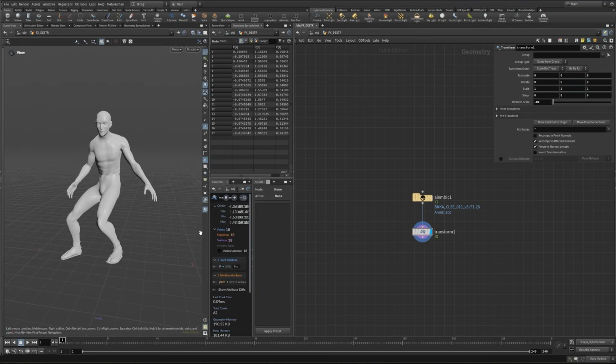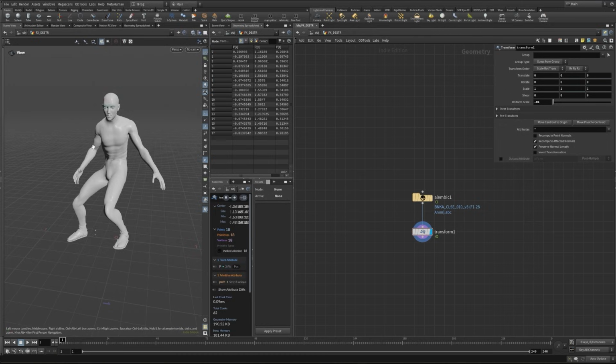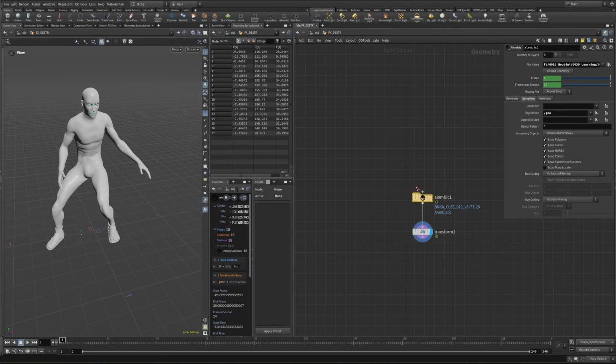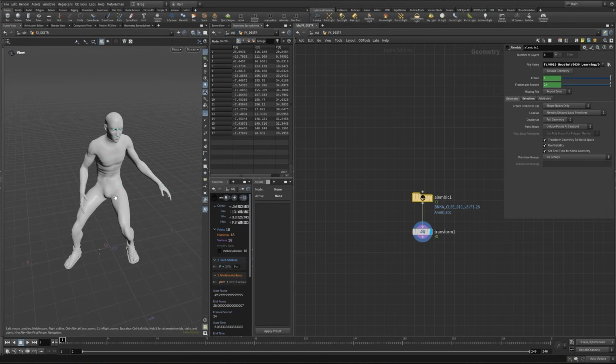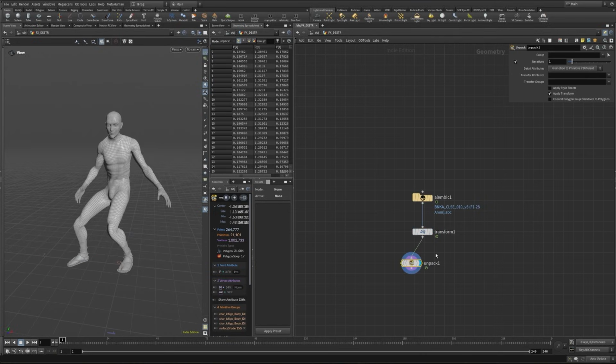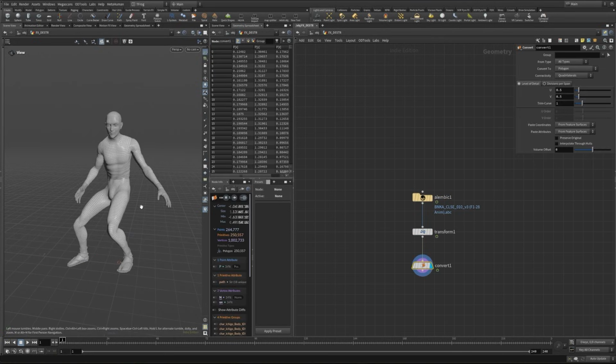This is looking good. But we will also notice the geometry only has 18 points. So it definitely has 2 less points here. And the reason is because it's an Alembic file, so it's packed normally. For this, we have multiple ways to unpack it or convert it back. So we can go unpack Alembic delay load primitives, or we could use an unpack node like so. Or another way I mostly use for Alembic is using a convert node here and convert it back to polygons.